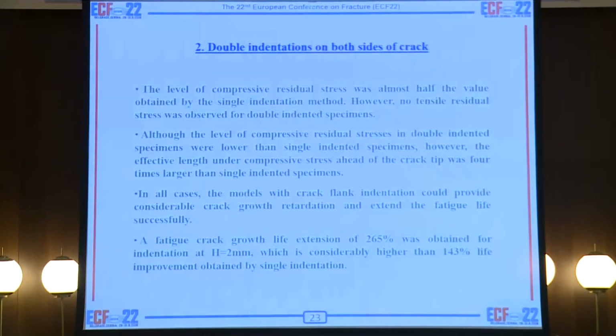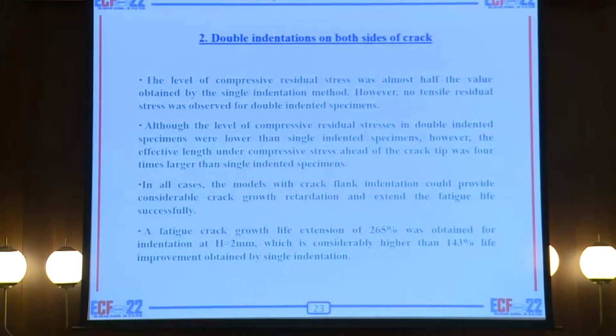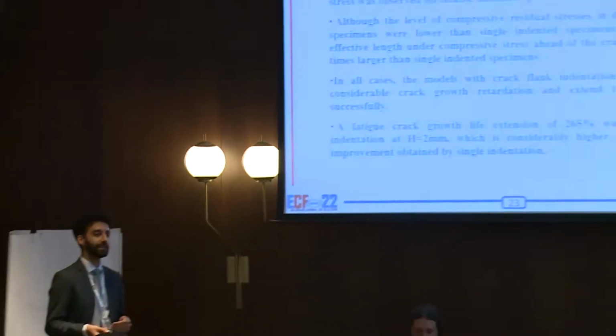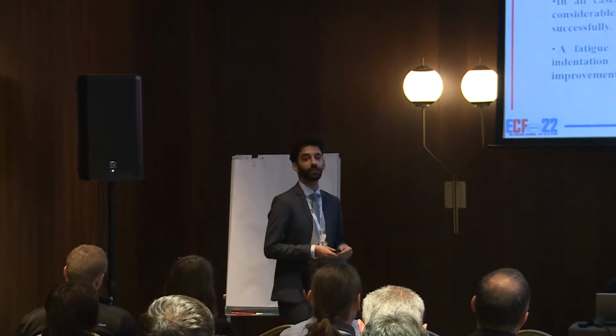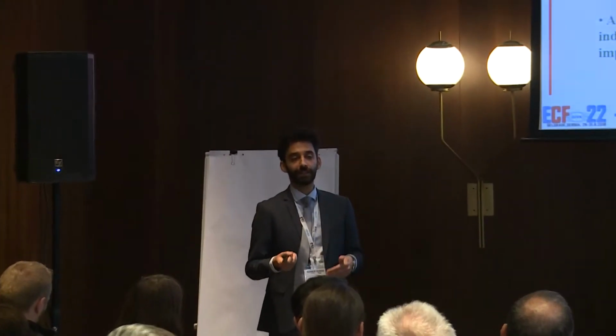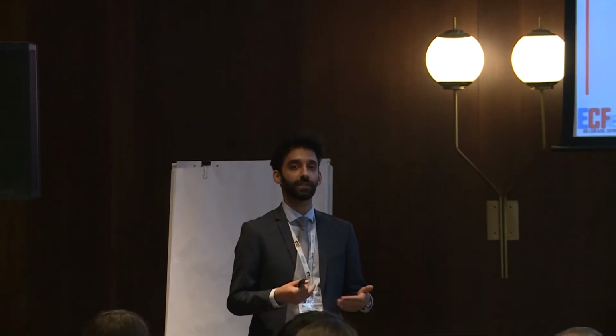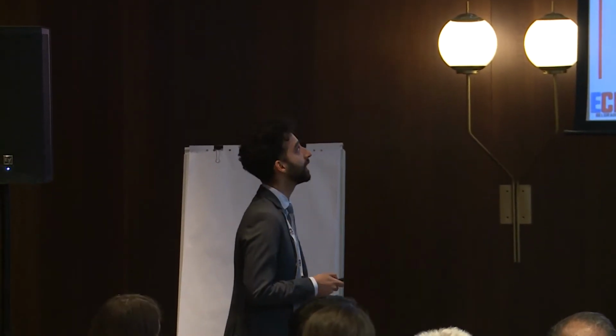And for the double indentation method, we saw that there is no tensile residual stress in front of the crack tip. It's all compressive, but the value is lower, but the effective length is higher. And that caused, at the end, higher fatigue crack growth retardation compared to single indentation.